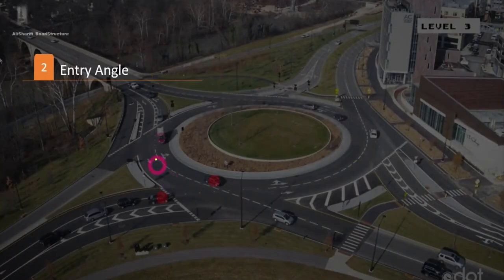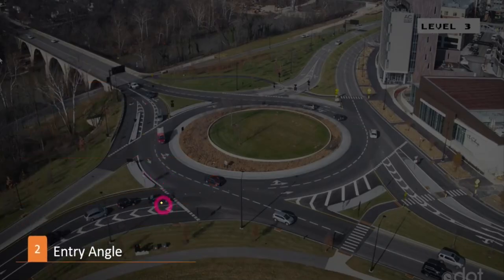Alright, first notice that the entry angle is not a controlling design parameter. Of course, according to our references and standards, Wisconsin DOT calls it a gauge of ease of entry to the right and side to the left. Actually, it helps us to get a better alignment for entries to improve both safety and capacity of roundabouts. Let's first demonstrate how we can measure it, and then we will discuss it.